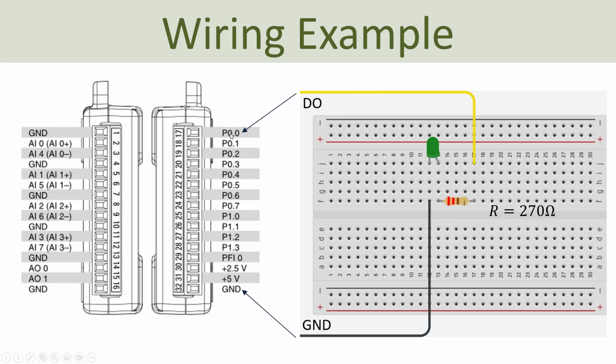So we can control all these digital channels to be either input or output, and we can also turn on either one at a time or turn off one at a time, or we can control multiple channels in one operation. So here we only need to use one digital channel, and it has to be a digital output channel. So that's something we specify in our application, if it should be a digital input channel or a digital output channel.